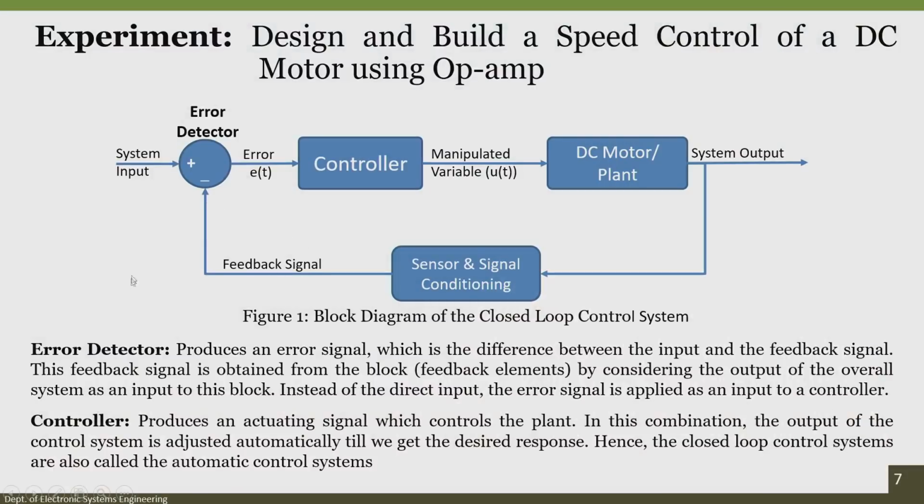By providing the output at this point, we can easily realize the complete closed loop system by integrating a DC motor externally and a controller which is sitting on the software side, and we can understand the complete working of it. We can understand the importance of an operational amplifier and the importance of a controller. We can also understand the working of DC motor speed control, in order to maintain the RPM of a DC motor by using data acquisition devices as well as software.